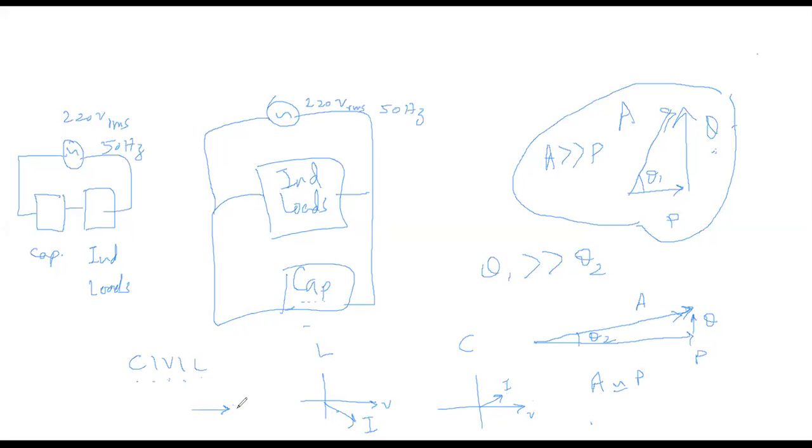That means it wants to make the V and the I vectors align, having a minimal angle or a zero angle. So in order to reverse the effect of the inductor, you attach a capacitor, and it is always attached in parallel so that the voltage requirement of the load is also met. Now, since the capacitor is a device in which the current is leading the voltage, we could modify this power triangle. Let me make some space over here.